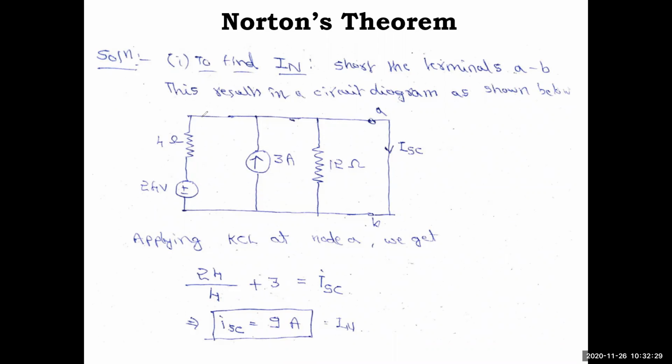Now if you look at the circuit, all of this is at the same potential, which is A, right? So I call this voltage VA. Now I will apply KCL here, or nodal analysis. There is a single node, and this side is the reference node, ground potential. One more thing here: if you have a closed path with a short circuit and a resistor, what is the answer? It is always a short circuit.